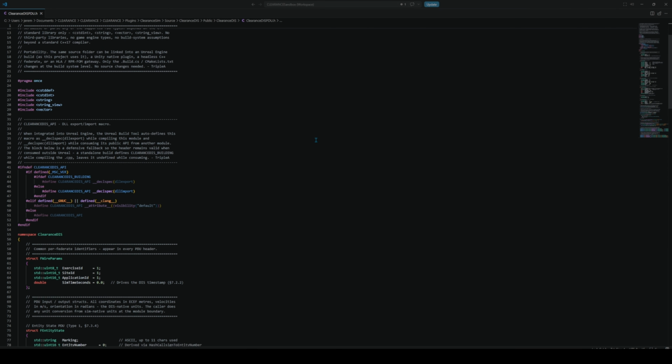This is what the legacy training rigs already run on. But the forward-looking work, Future Airborne Capability Environment avionics, autonomous wingmen, that's all built on DDS, the OMG Data Distribution Service standard. RTI Connext leads the commercial markets. eProsima Fast DDS is the open source C++ implementation. This is what the new defense systems talk on.